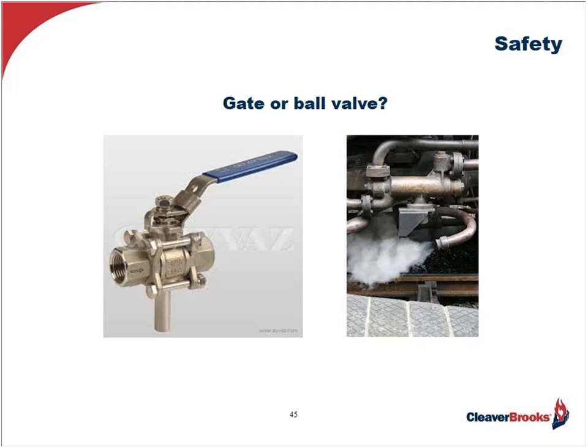So if this might be the case in a facility, or one that you know of, the recommendation by the expert will be to replace this valve with a slow opening gate valve to greatly mitigate the chance of this possible scalding situation occurring.